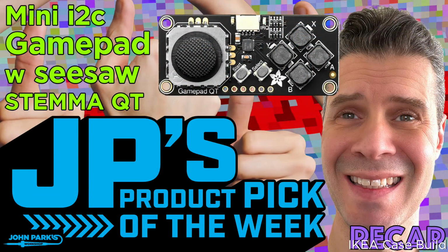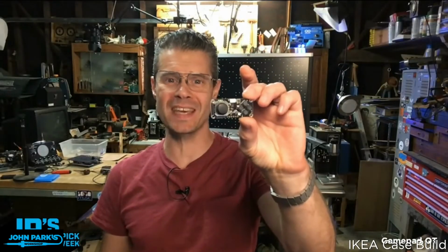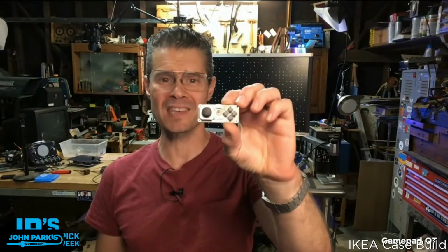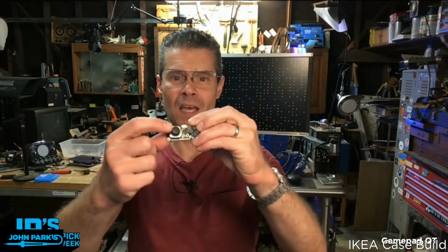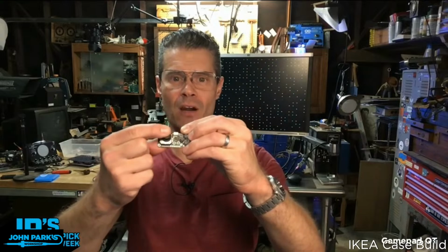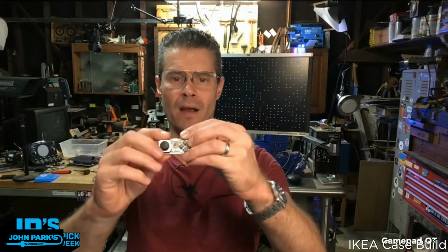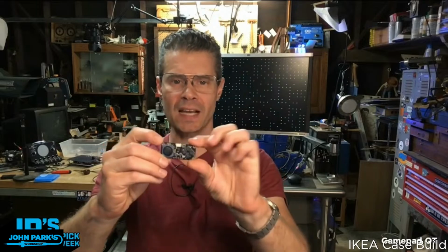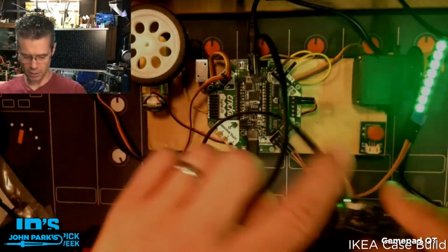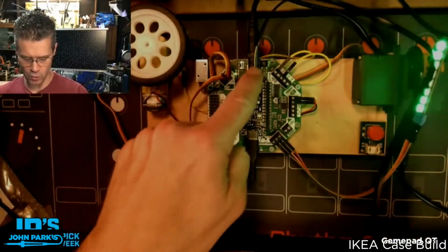It was this mini I2C GamePad. Here's a little one-minute recap. It is the GamePad QT. It is a Seesaw chip-based STEMMA QT connected GamePad. It has the two-axis joysticks, that's an analog dual potentiometer right there, as well as the four ABXY buttons and start select. GamePad QT plugged in over STEMMA QT cable to the Feather board.